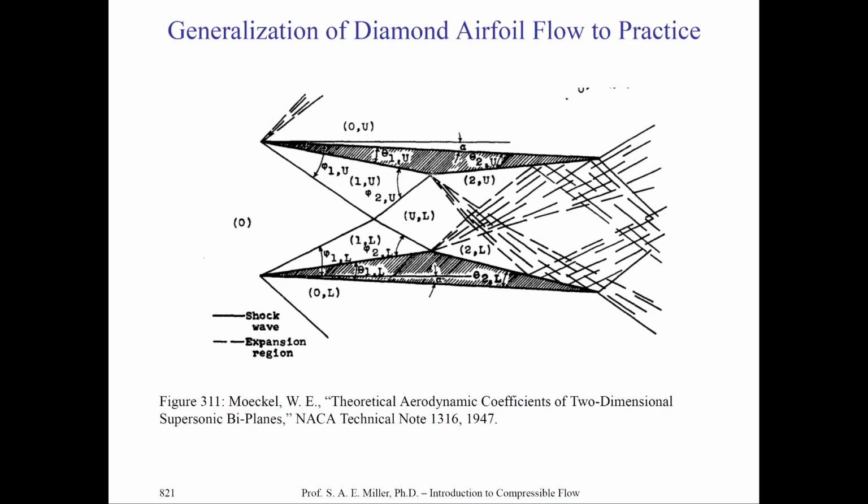Like we talked about in the reflecting shock wave case, for certain wall turning angles, they will either reflect as a shock, nothing, or an expansion. In this case, you can see the flow after the shock wave indeed must be turned and be parallel to the wall, and therefore an expansion wave forms at the tip where the shock wave hits the wall. And therefore, in this case, if we turn the wall out of itself relative to the flow, if you will, in slang, we can form these expansion waves. Take a few minutes and try and understand the physics of this.